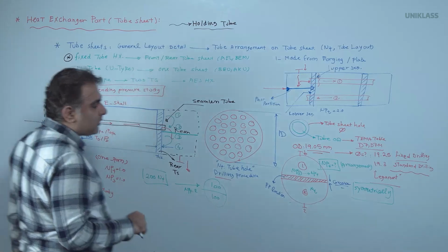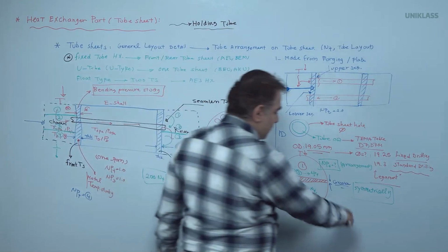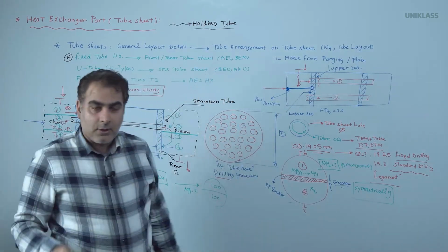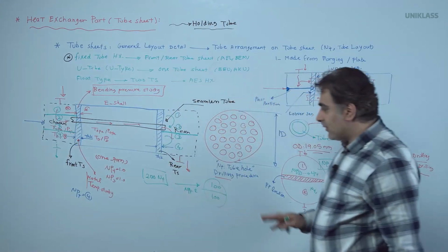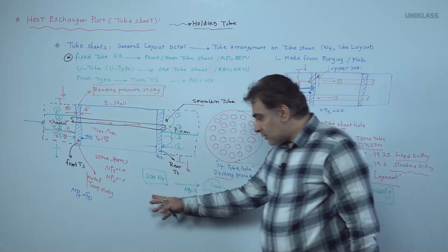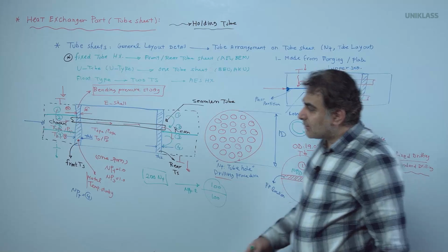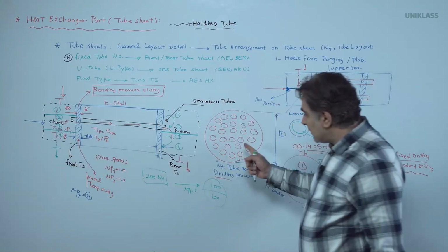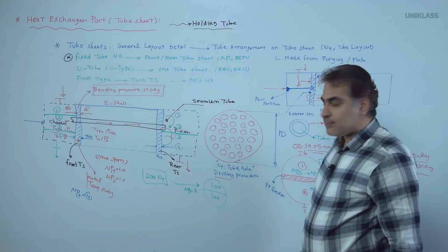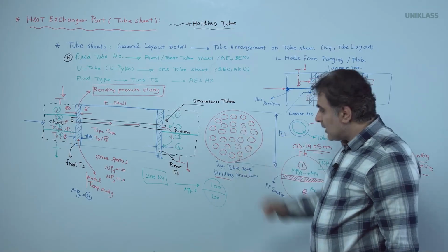Generally, we need to model symmetrically. All software like HTRI, Aspen EDR, or maybe your hand calculation software deliver to us the number of tubes. But we need to generate the path partition detail on the channel, and the detail shall be mentioned on the tube sheet layout.